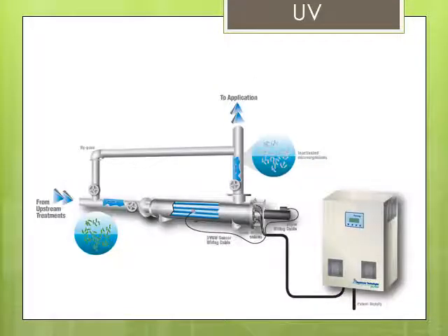Looking at UV is where basically you've got waterproof quartz tubes that have UV lamps in them, and water is passed around the tubes where they're exposed to the UV light, and then they exit. Now, UV light is bactericidal because as UV light shines through the water, it shines through the bacteria and the viruses and the spores, passing through their relatively thin cell wall to the inside of the organism.